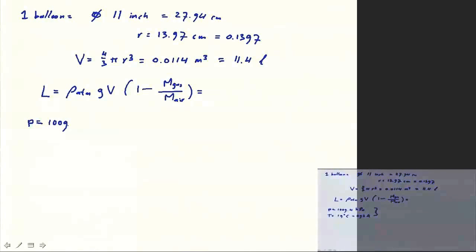The density, then, we can calculate: P divided by RT, and now we have to be careful to use SI units. This should be Newton per square meters, because it's hectopascal on the other side, so we multiply by 100, and then we get the Pascal or Newton per square meters.